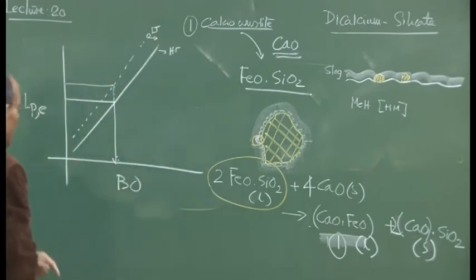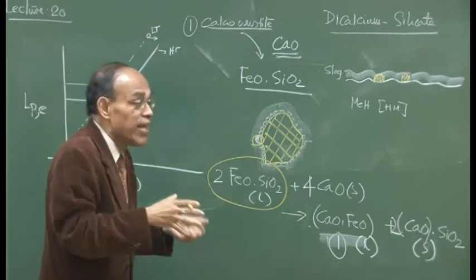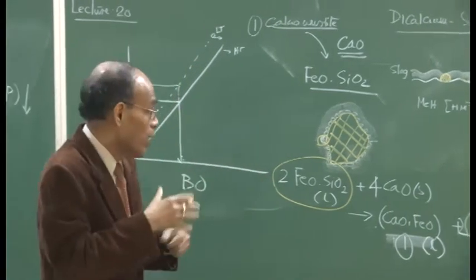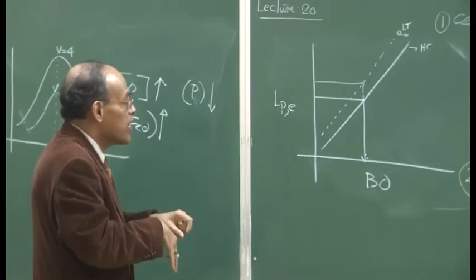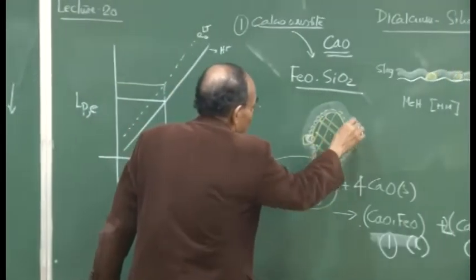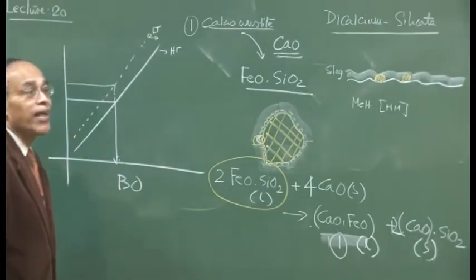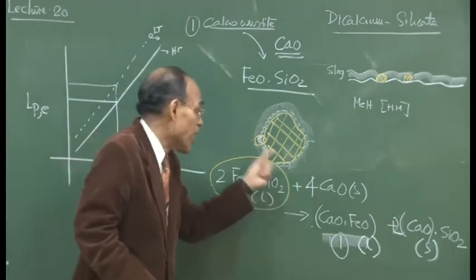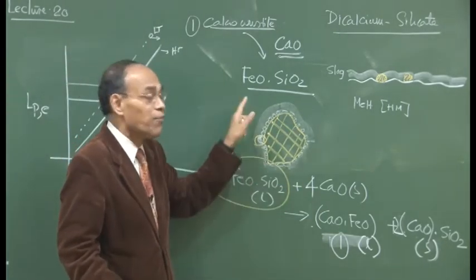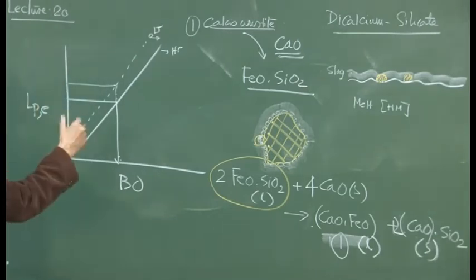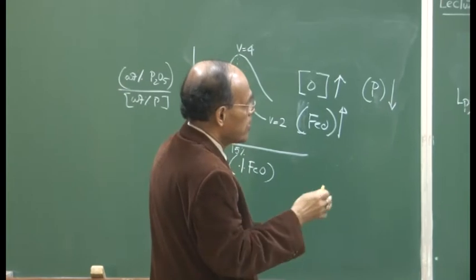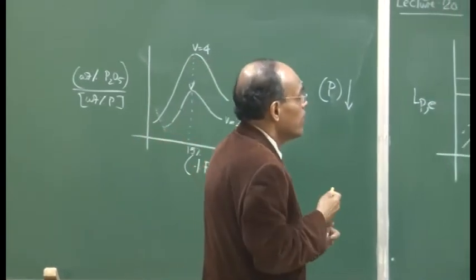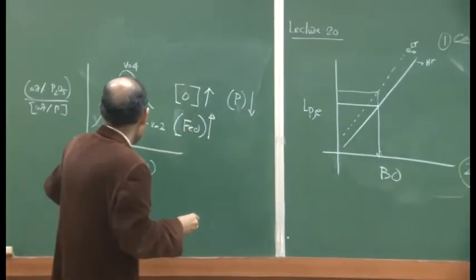So if we say x weight percentage of SiO2, we are aiming at 4x weight percentage in the slag itself. So the lime remains in the dissolved state, and that dissolution is not going to be possible if it is coated by a material which is solid and which has gotten sintered with the lime surface itself. And we will discuss this later on when we talk about what we call the slag making during the oxygen steelmaking process.